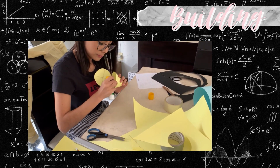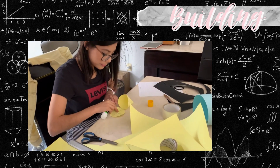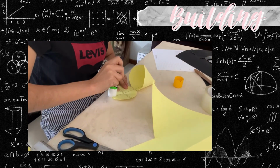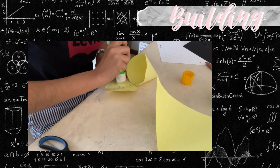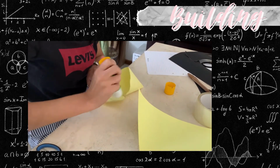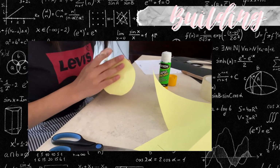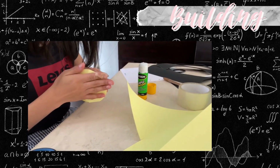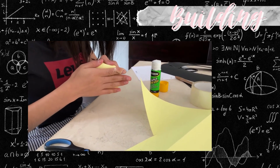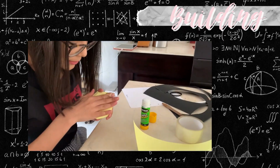For this specific figure, we had to calculate the generatrix of the cone. To obtain it, we used the formula of the square root of the square of the radius plus the square of the height. As well, we had to calculate the angle needed to build the body of the cone by following these steps. First, we multiplied the generatrix times 2, and then we also multiplied by pi. Then we calculated on a scale of 360 by a rule of 3. After that, we obtained that our angle was 109. With all of this in mind, we proceeded to make the figure.